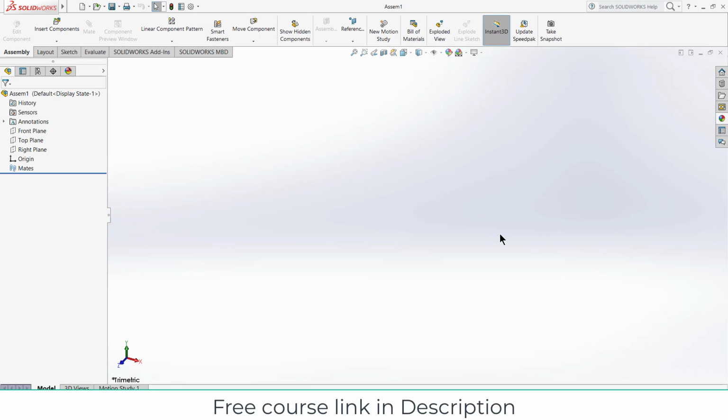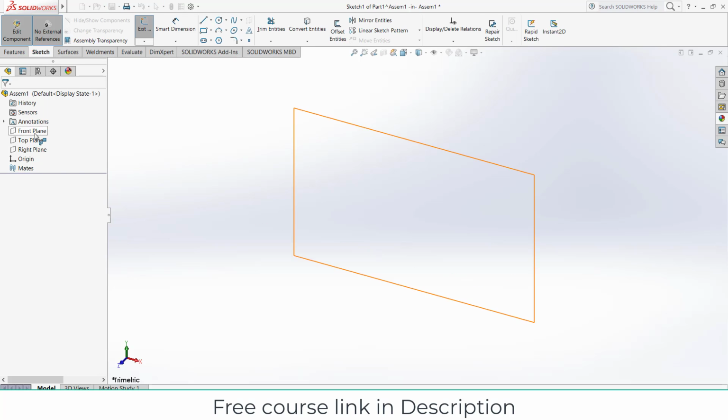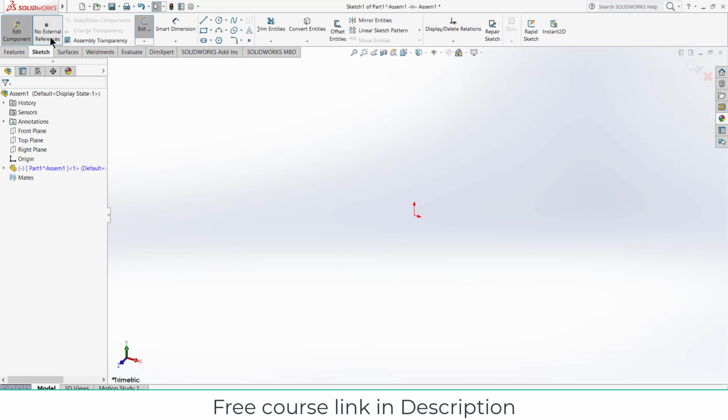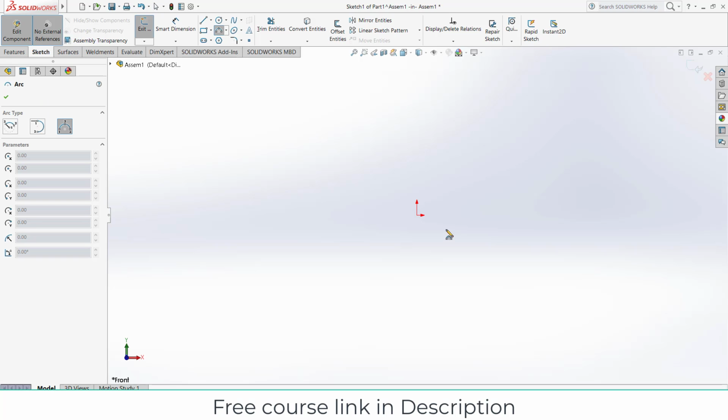Okay, so let's start. First click on insert, click on new part, select the front plane, and make sure that you click on no external preferences, else you will face problems later onwards. Now press Ctrl plus 8 for normal to the view. Now click on 3-point arc.